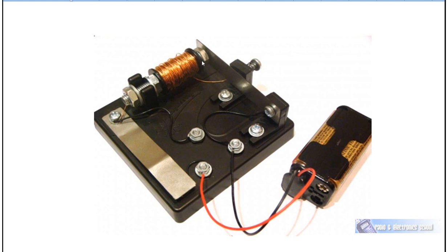So when a current flows through this magnet, both ends of the bolt become very strongly magnetized with a north and a south pole. When that happens, this armature here, this moving metal vane, is pulled inwards to the metal bolt, and that breaks the circuit.